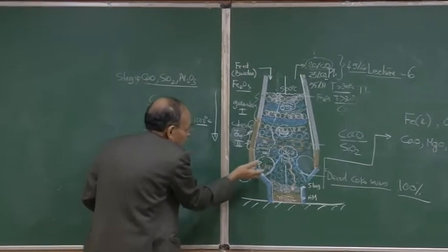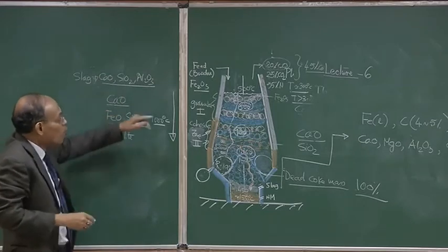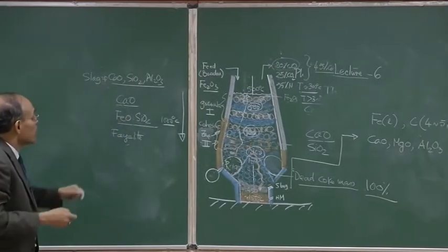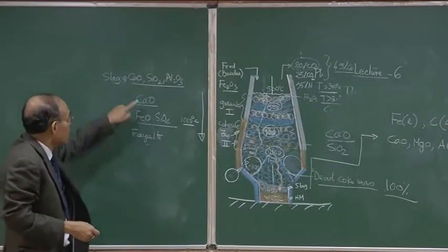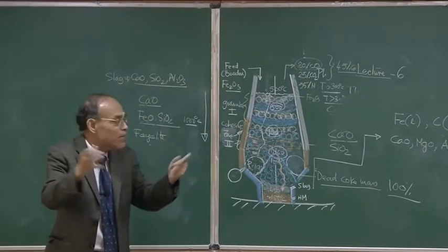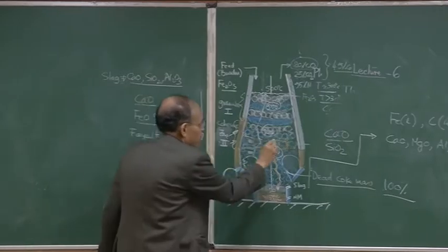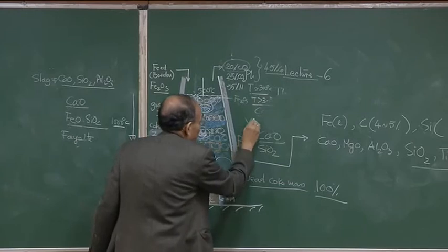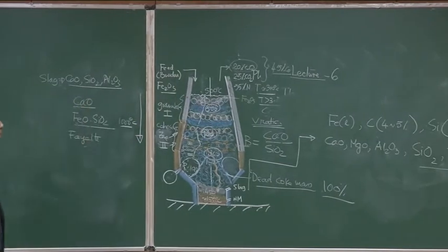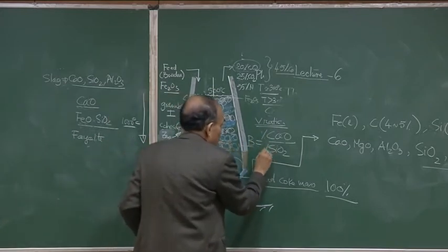This coke is burning, ash is being liberated. So, the silica is taken up and then the basicity of the slag is progressively changing as it is descending down because of the various reactions taking place, that progressive replacement of FeO by CaO and continuous dissolution of silica and alumina into the slag dynamically changes the basicity of the slag, which I have defined. The simple definition is called the V ratio. There are other definitions of basicity also, which we may see later on when we do steel making, but it is sufficient for us, and these are weight percentage CaO versus weight percentage SiO2.